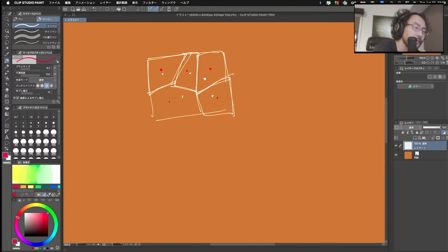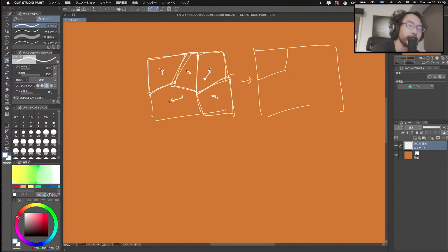Okay, so you first calculate the centroid of the Voronoi cell, and using an iterative method, something like a solver, move this point over to the centroid of the polygon and recreate the Voronoi using this new centroid position, which will create a bit more distributed result compared to the last one.